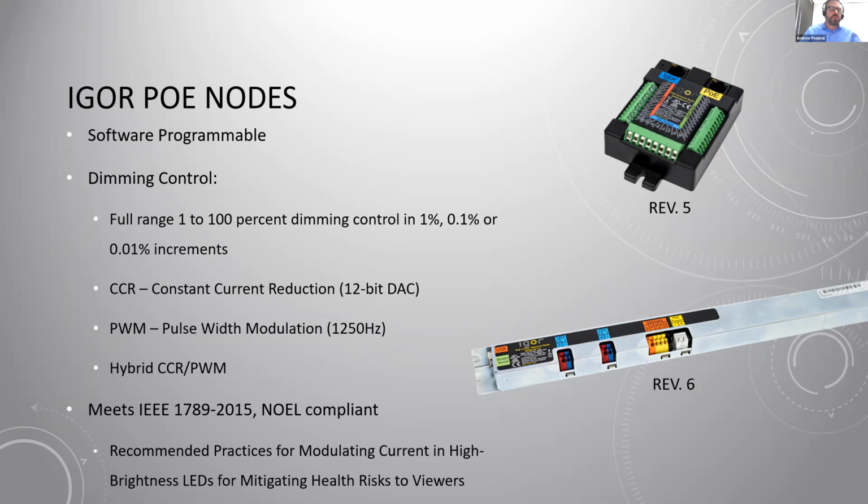One of them is our software programmability. So with the same node, same physical device, you can program it for different milliamp levels, different inputs and outputs for different sensors and such, wall switches, relays, etc. Very flexible, and all of this programming can occur over the network. So you don't have to physically access the device. You can use some different features to identify its IP address, and update its programming.